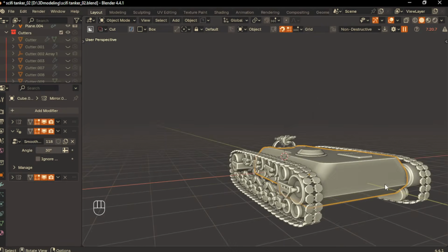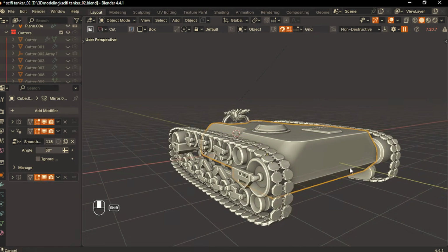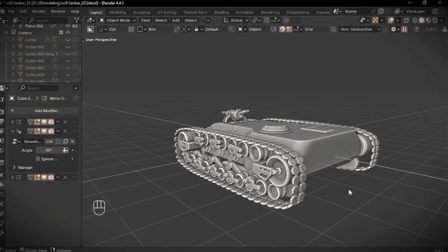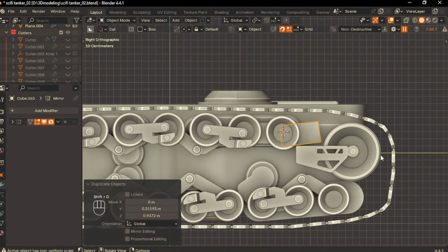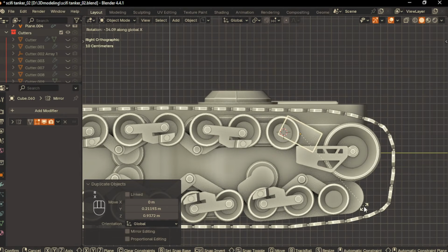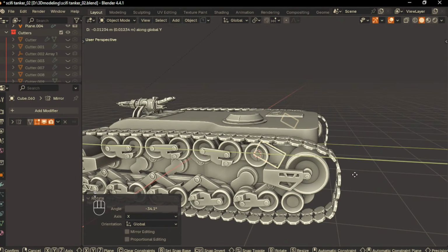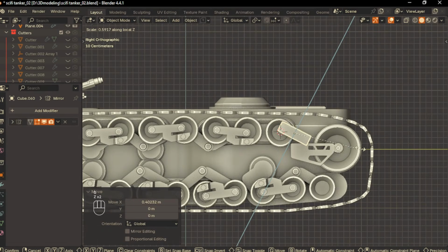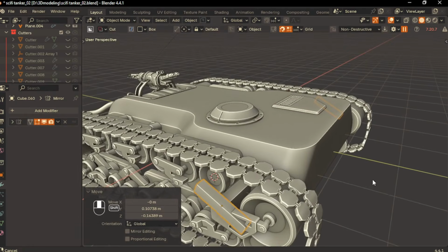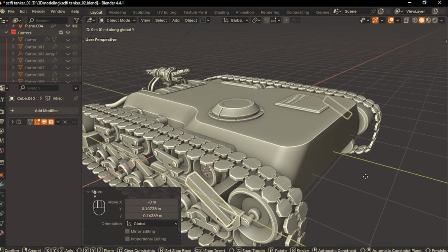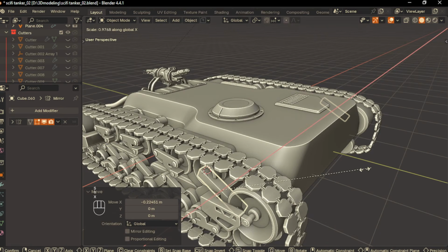Now let's complete the wheel mechanism. As we already built the main structure, we still have a few wheels left to connect. So I'm going to duplicate this plate and move it upward. Then rotate it on the edge just like this and bring it forward. Now let's scale it down on the local Z, the Y axis to adjust the proportions. Once done, position it properly. We can push it slightly back, make it thinner and move it forward again to balance the design.